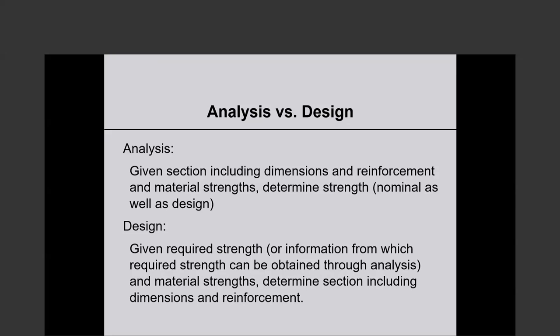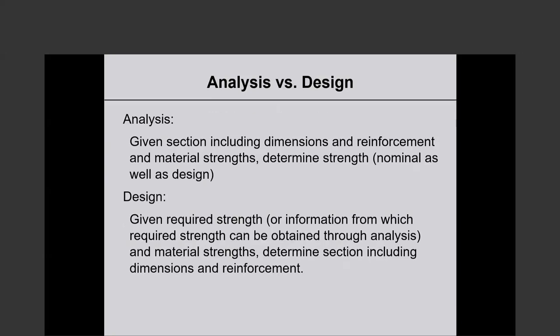Given required strength, how much is required, or information from which required strength can be obtained through analysis. So given required strength and material strengths, determine section, including dimensions and reinforcement. So that's design.